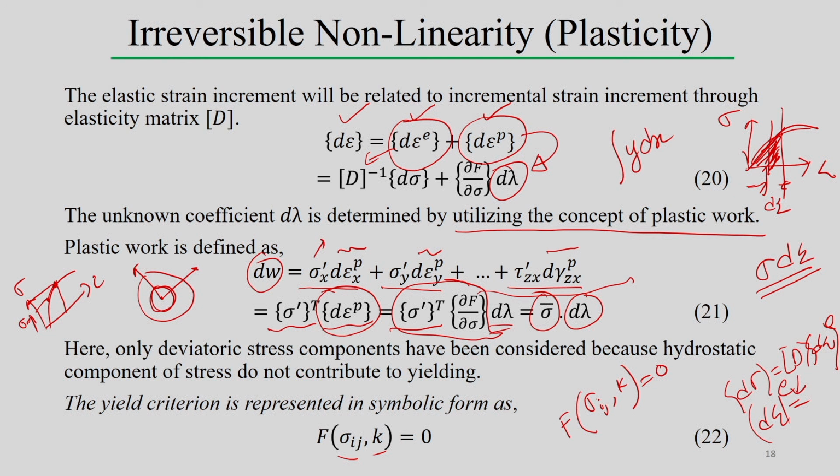That way the yield surface, or yield point, evolves in either a uniaxial or a 3-dimensional state of stress. So, k takes care of this hardening effect, and sigma ij is the particular state of the stress. Combining these two we can represent the functional form of the yield surface.